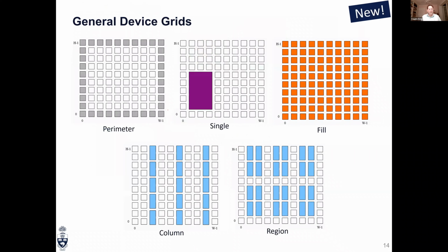Okay, once you've decided that these are the primitives that my chip's going to support, and this is how they're arranged into somewhat bigger blocks, you describe how that is laid out on the chip, what we call the grid. So, for example, I might decide that I'm a cheaper FPGA and my IOs are around the perimeter. And inside I've got logic blocks. I might decide I've got one big hard block, a processor subsystem. There's just one of those. I've got some other keywords saying just fill this whole region with something, maybe logic blocks, and so on. So there's a bunch of easy to use keywords to specify the two-dimensional arrangement of these blocks that I've defined in the chip.